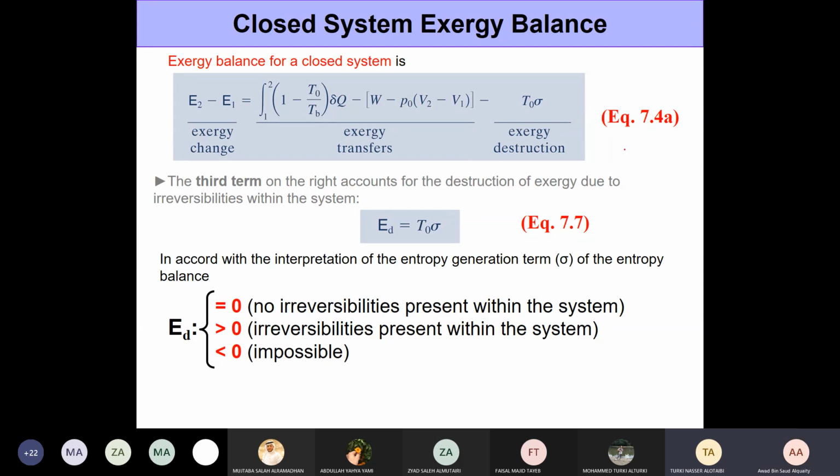Yes. So we're not saying that energy is being destroyed. We are saying exergy is being destroyed. And the reason we say exergy is being destroyed is because some energy transfer is happening to things which we do not want to happen, right? As a very simple example, if you're talking about expansion within a turbine, as the fluid expands within the turbine, there is some friction associated with the expansion process.